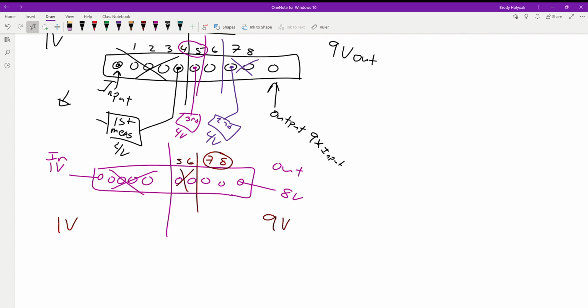Whereas, we could have started with stage 1 and checked all the resistors in that circuit. Okay, they're good. Jump to stage 2, check all the resistors and transistors and the capacitor in that circuit. Okay, they're good. Jump to stage 3, stage 4, stage 5. Half splitting gives us the option to not have to spend so much time. And in industry, anytime you can save time is a big deal because that is money.